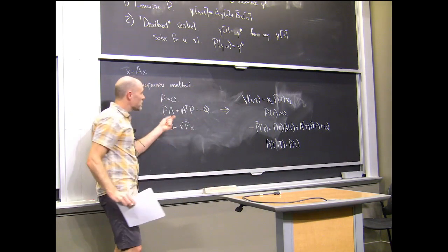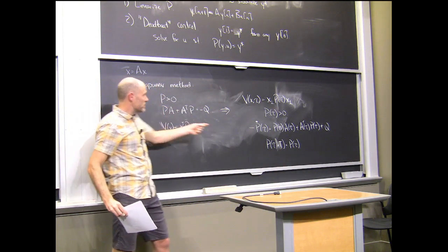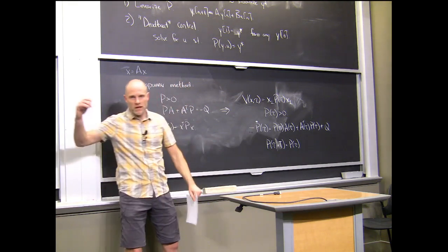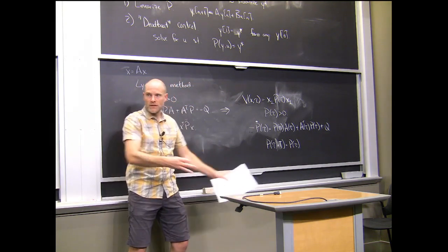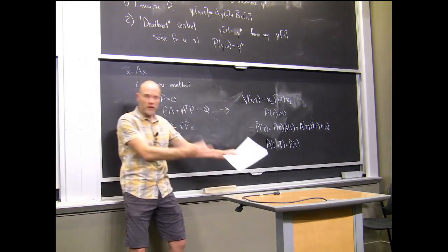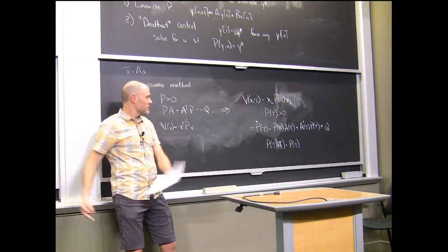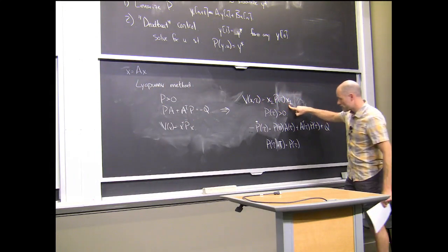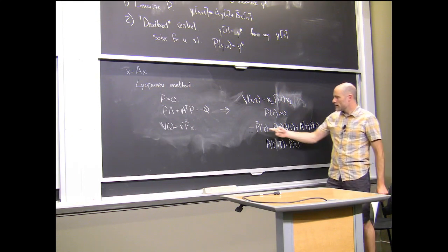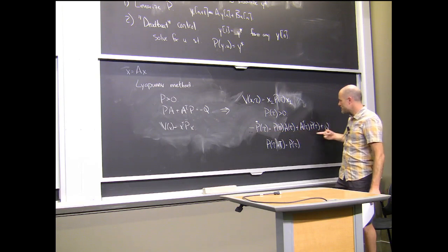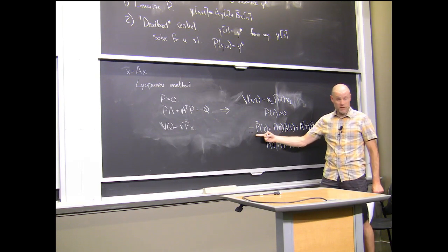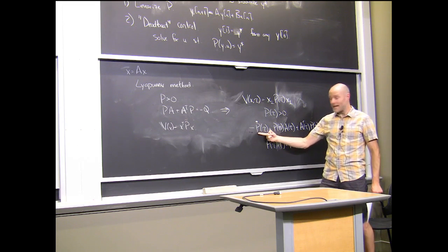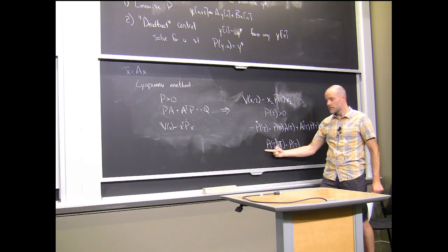Okay, so what I said here is just a natural analog to that. That's just the time-varying version of it, just like we went from LQR to time-varying LQR. We have Lyapunov to time-varying Lyapunov. We'll have the same thing, and now this is in the transverse coordinates, okay? And what we want to do is find a solution to this Lyapunov differential equation that is a periodic solution. We want to find one that's like this.